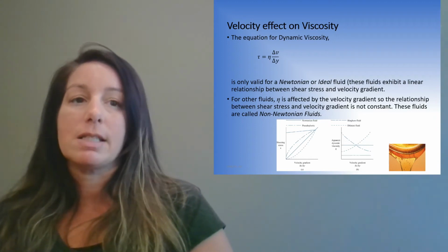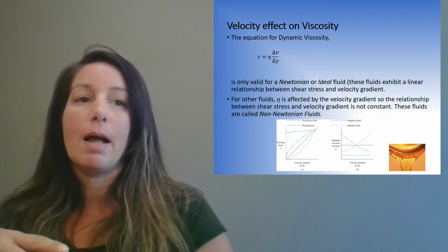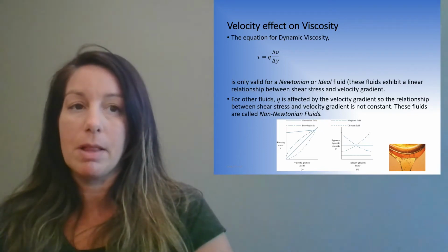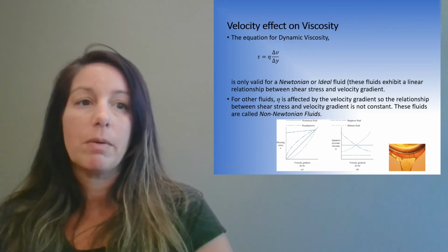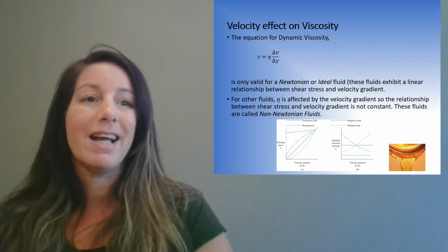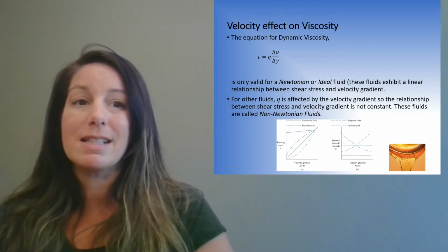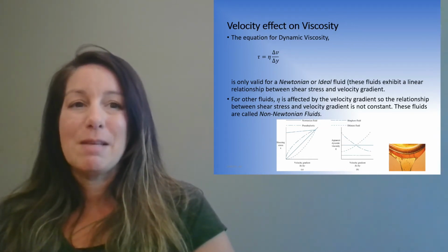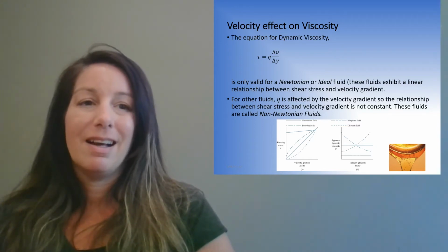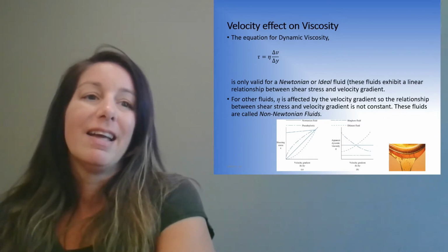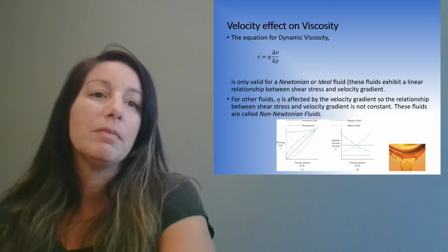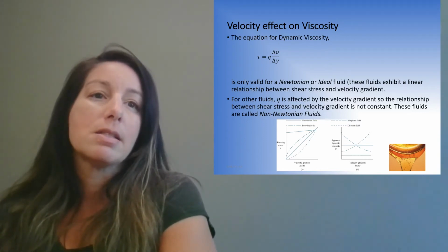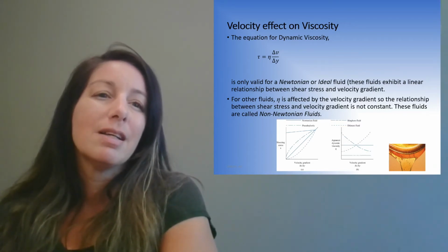So that's shear stress. If we look at the other graph B, we've got the apparent dynamic viscosity, that same constant, right? It's not a constant in these other cases, right? So for a Newtonian fluid, it's a constant. Again, it's that same concept. It's just a line. And what else do we have here on this velocity gradient? If we look at the Bingham fluid, well, look at it.